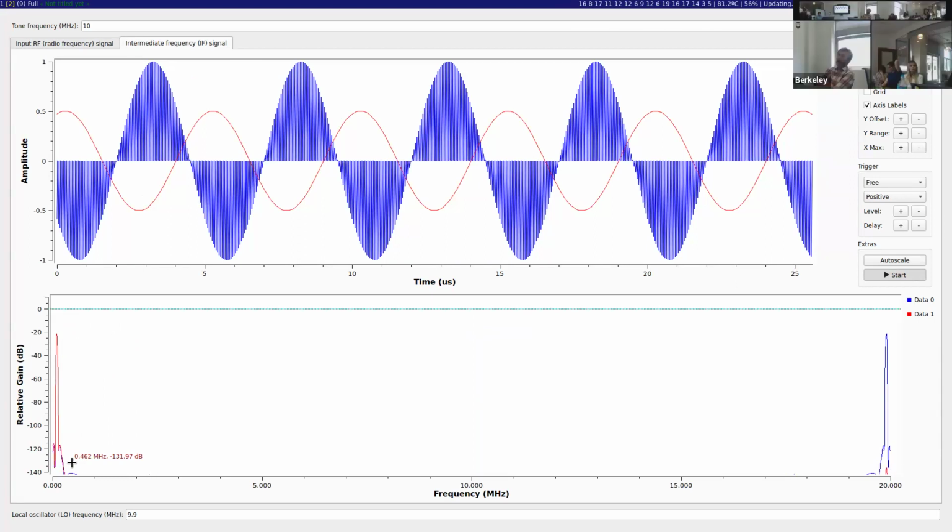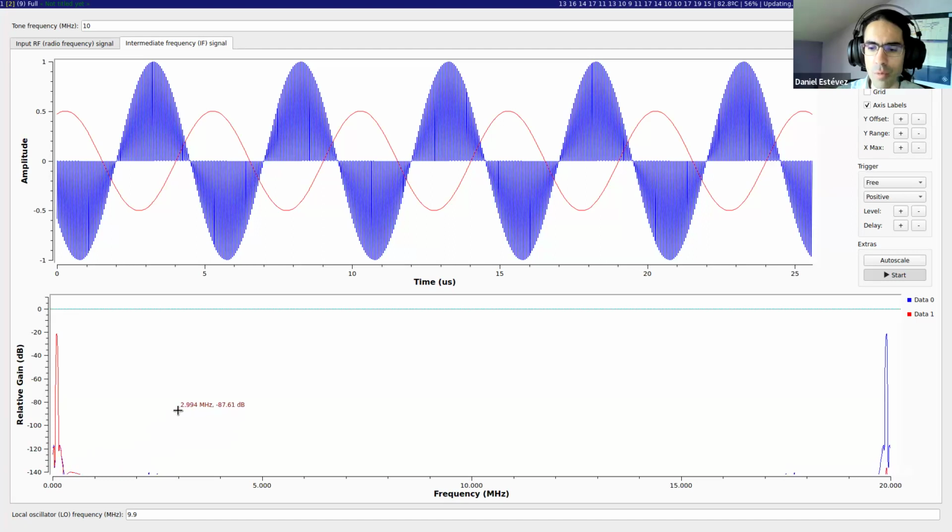I mean, I guess to put it another way, if you left the low pass filter out in an FM radio, would you hear a difference in the audio? It depends on which low pass filter, because between the antenna and the audio output, there are several low pass filters, and we will see where each of those are.